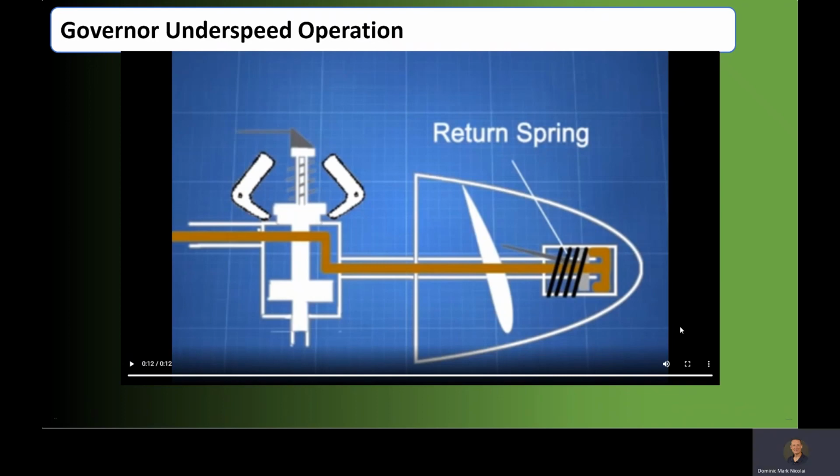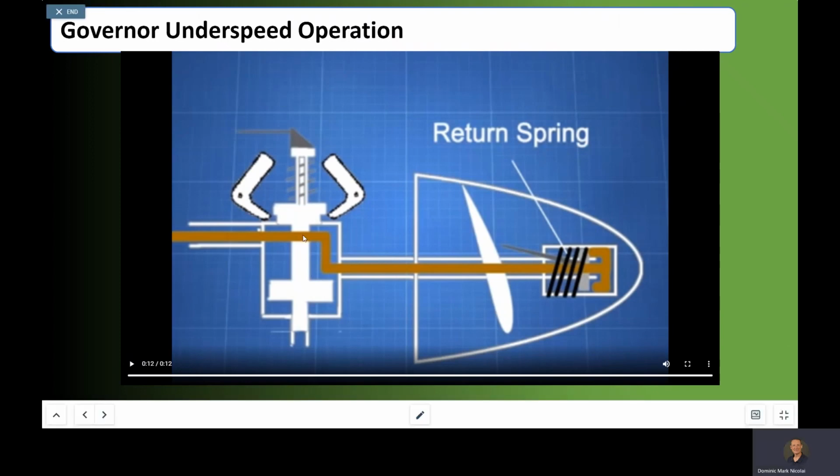Plus you got the counterweights, asymmetric twisting moment, and the air charge up in there, all acting one way. The only thing that opposes that is the oil pressure the other way. So when the pilot valve opens up, all of these forces, the spring, the charge, counterweights, ATM, push that piston the opposite direction, and the oil is forced out back into the reservoir.